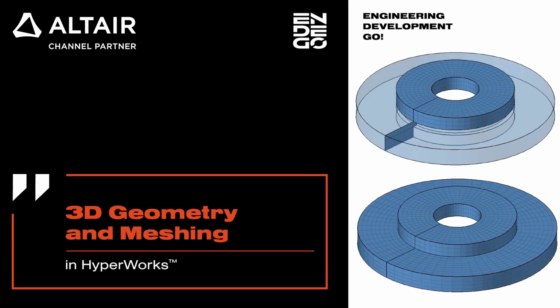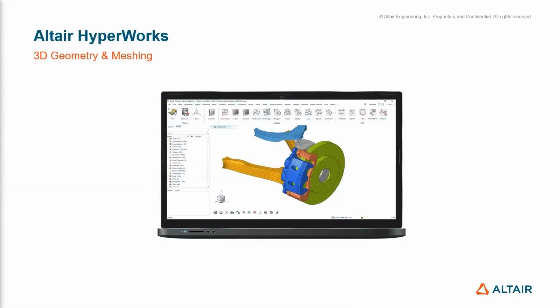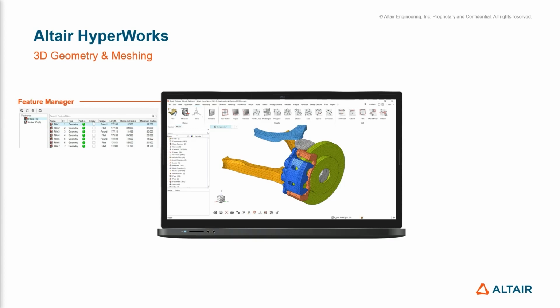The focus of this session will be 3D geometry handling and meshing in HyperMesh, and how we can quickly and efficiently generate solid mesh. Firstly, we will look at the Feature Manager and understand how this combines automatic feature recognition and tabular management to quickly identify and edit or remove particular features.